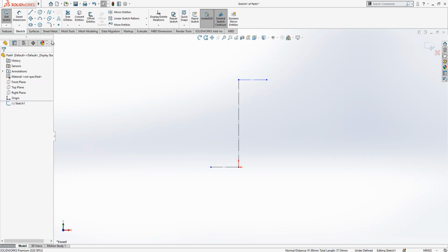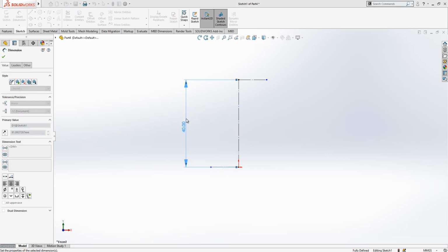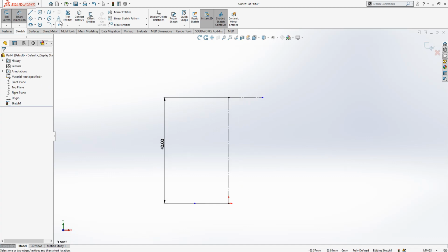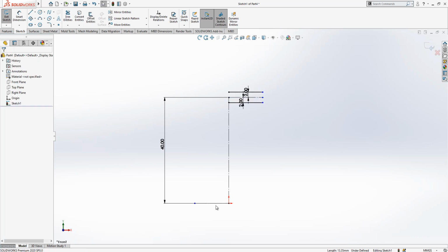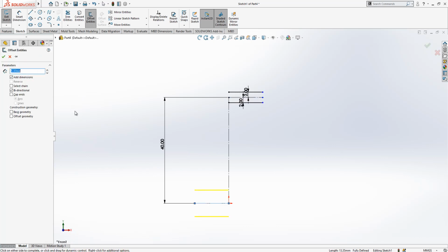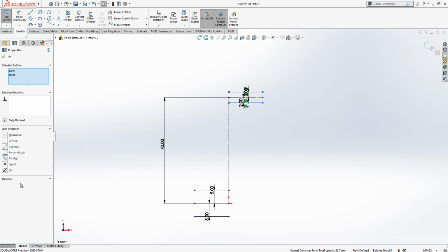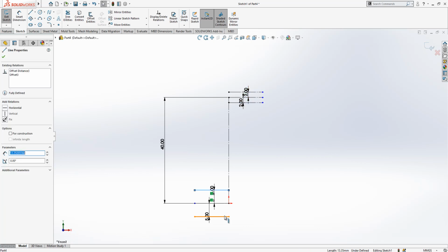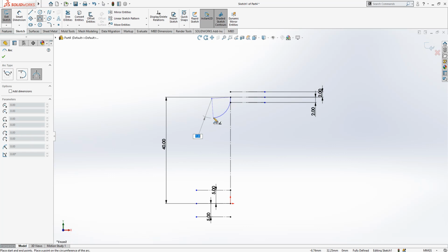These two can be equal to make sure that our sketch is looking neat. This is 40, and now here we can create a bidirectional offset with 2 mm. Bidirectional should be active, and here we are going to create 5. In total we will have 10 mm difference between two line dimensions. Sorry, I made all of them construction geometry, and I'm going to add my first items.